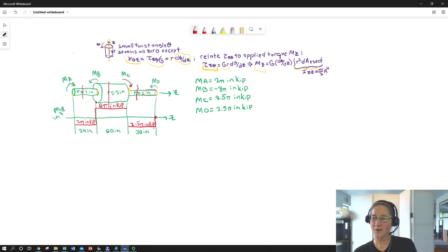And thankfully, what we find from that is that at our end point, our final applied torque at M D will basically be providing this, so we stay in static equilibrium. So what we've got in this diagram are basically values of M sub Z that are non-negotiable. We're not creating them by some kind of twisting angle that then we have to figure out the moment that we had to apply to get it. This is the applied moment. And so the internal moment in the shaft over those sections is fixed. So when we do our calculations, those are constants.